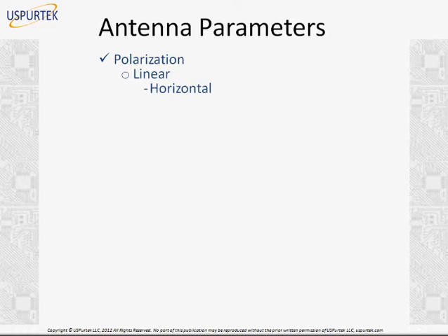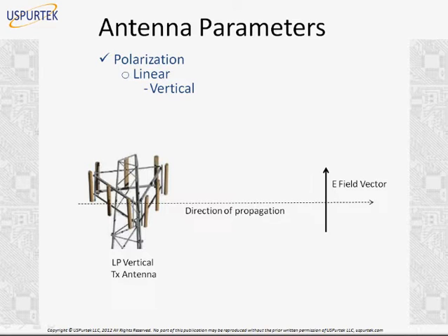Let me go back a little. So, linear vertical polarization. Typically in telecom we use vertical polarization, because if you see the cell towers, these rods are in the vertical direction, and so are the handsets that people hold in their hands.